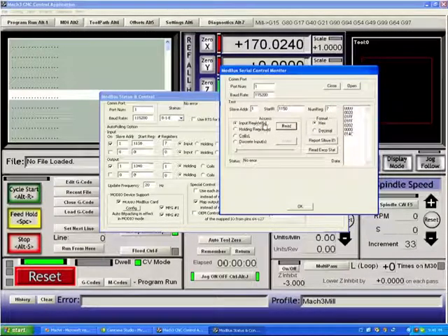These are registers coming back into Mach3. So for example, on Peter's board, you'll have 8 input points that you can tie to, which are exactly like the pins on a printer port. His pins start at address 1150. And there are 7 addresses of information that we can read from his ModBus. So you can see I've set this to slave address 1, start register 1150 for 7 addresses. Each address in a ModBus is 16 bits.